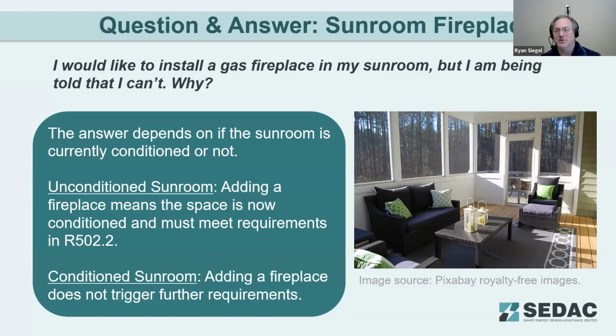Right. Sunrooms. Want to add a fireplace to my sunroom. So the question came in, want to add a gas fireplace to the sunroom, but being told that that's not code compliant. How come? And so part of this is recognizing this may depend on if the sunroom is currently conditioned or not. And if we have an unconditioned sunroom, adding a fireplace now would move this from unconditioned space into conditioned space. And now we have a change in space conditioning.